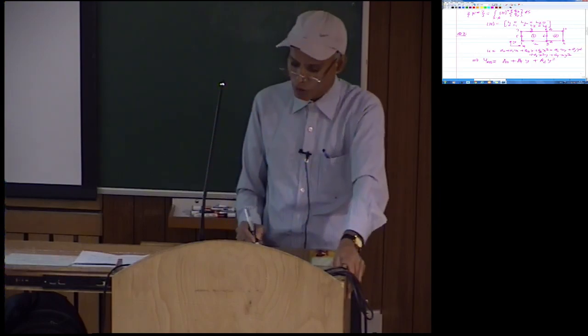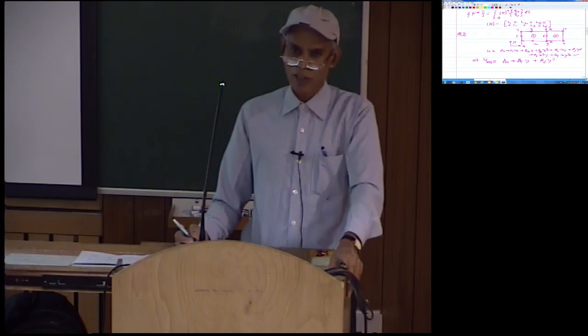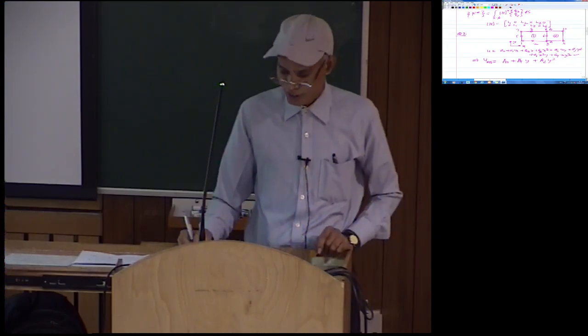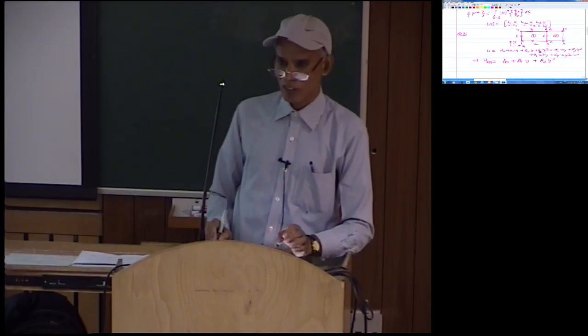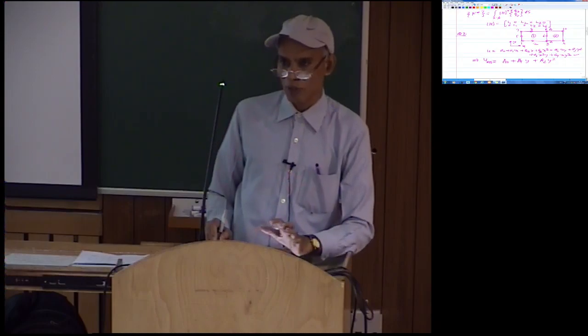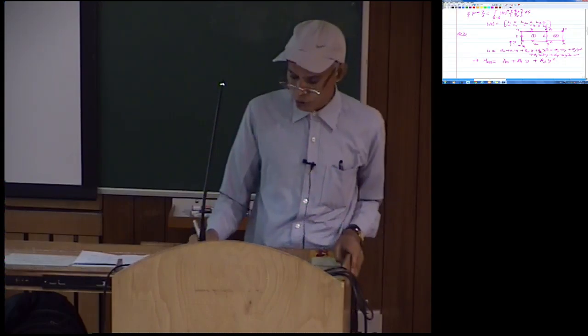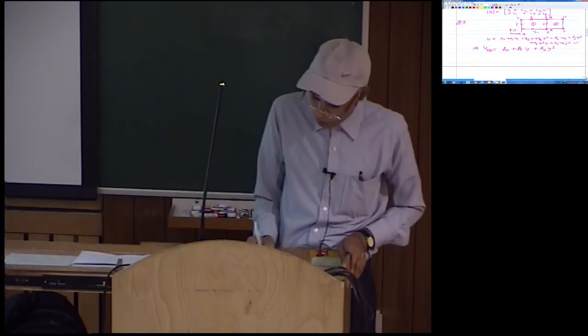Now if you are looking at variation of u along AB, wherein your x coordinate is constant, once you put x coordinate constant, this would be something like a0 plus a1y plus a2y square. This is the form when you put x equal to constant, because there is a constant term, a linear term, and a quadratic term of y. Even if you take x as some general equation of a straight line, then you will have this as cubic, the other one would be quadratic, and still you will have a mismatch. So this is for the first element.